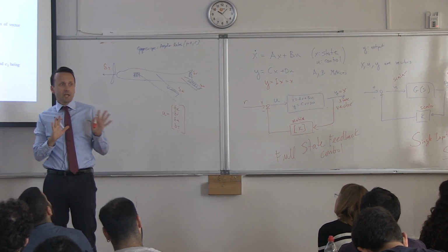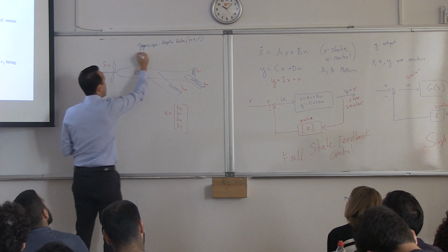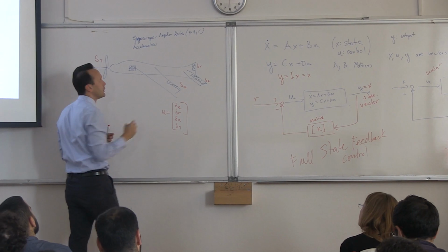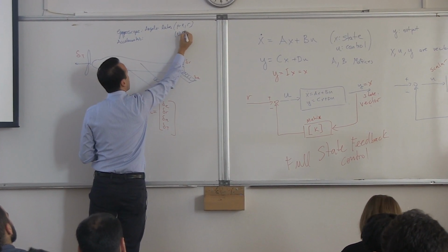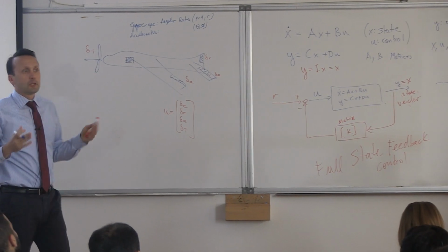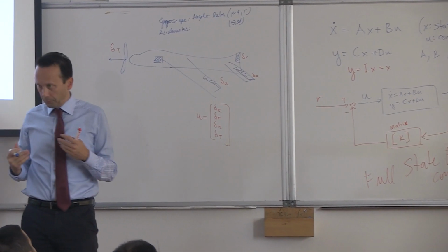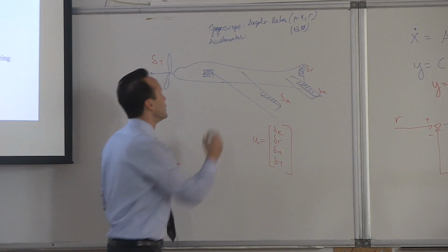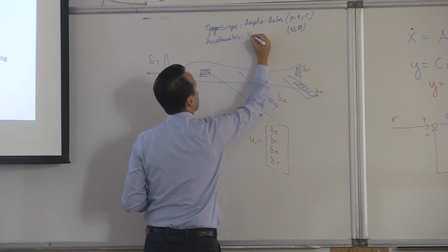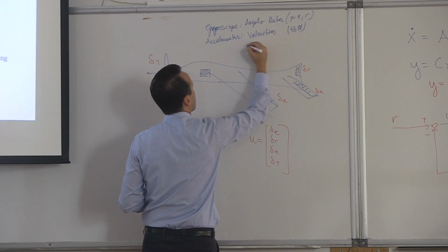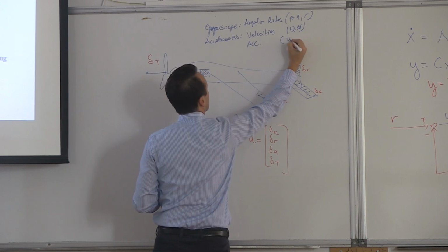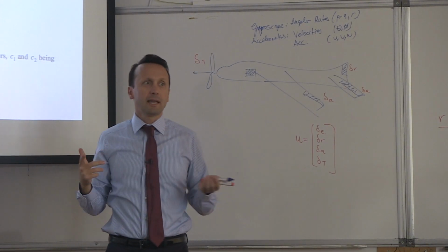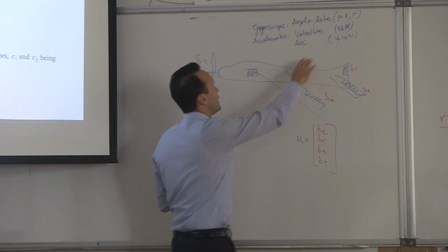If you initialize everything right with a set of accelerometers, you could even estimate theta and phi. With accelerometers, obviously you measure acceleration in each direction, but if you take an integral appropriately, you could also measure velocities. So you would get U, V, and W, the three velocities in the body axis system. So you measure all this.